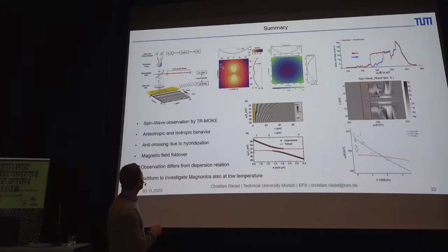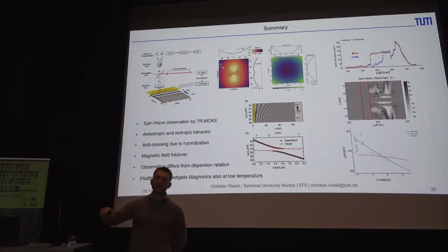So if you do a spatial FFT of your coplanar waveguide or of your antenna, that gives you the excitation spectrum which you can actually excite. So you can excite shorter wavelengths, but this is inefficient with such a big, more or less macroscopic coplanar waveguide. And furthermore, we would not be able to measure them. So we are limited to 300 nanometers in our wavelengths.